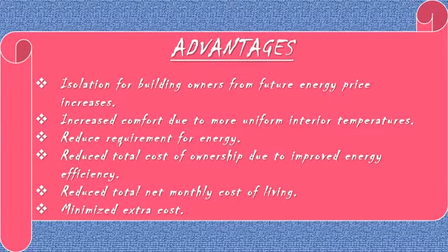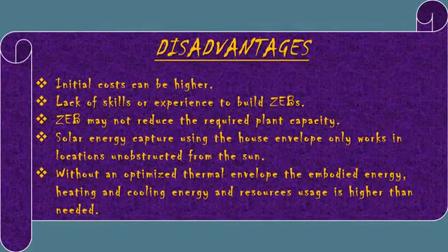Now the advantages of net zero energy residential buildings. Isolation for building owner from future energy price increases, increased comfort due to more uniform interior temperatures, reduced requirement for energy, reduced total cost of ownership due to improved energy efficiency, reduced total net monthly cost of living, minimized extra cost. And disadvantages are initial cost can be higher, lack of skill or experience to build zero energy buildings.